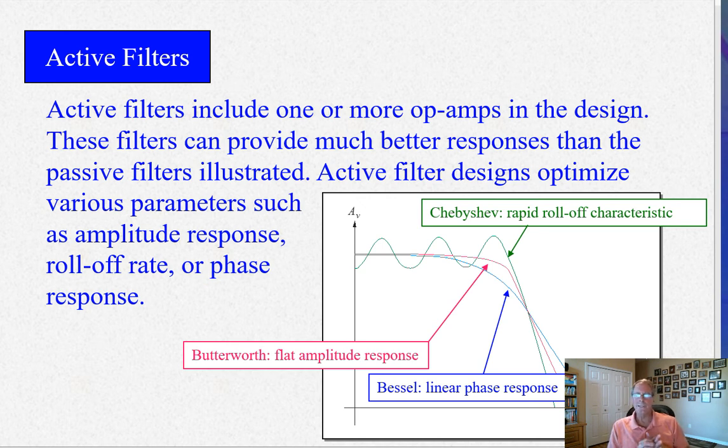And the reason that's important, why Bessel filters are used to keep phase response linear, is for non-sinusoidal signals, signals that are not sine waves. For example, square waves. Square waves are made up of an infinite number of odd harmonically related sine waves. So 1 kilohertz, 3 kilohertz, 5 kilohertz, and so on. It's a Fourier transform. All of those frequencies have to have the same phase if you're going to filter it, okay? And then retain that square wave at the output. And a Bessel filter is used to filter non-sinusoidal waveforms like square waves and so on.